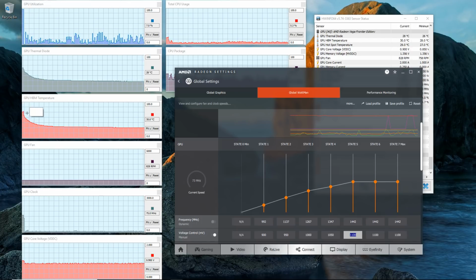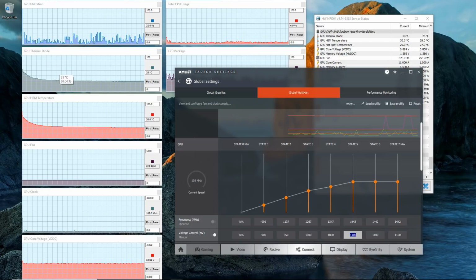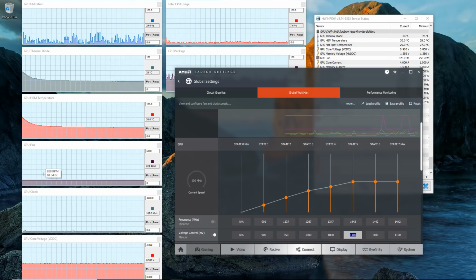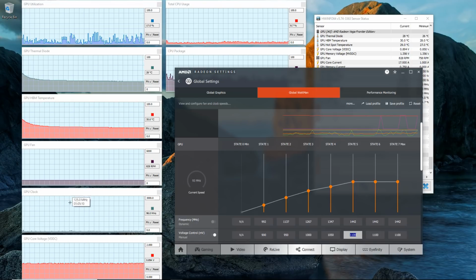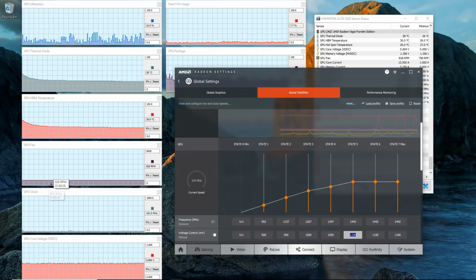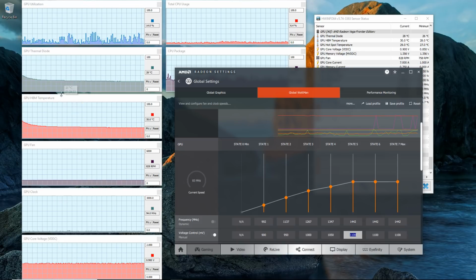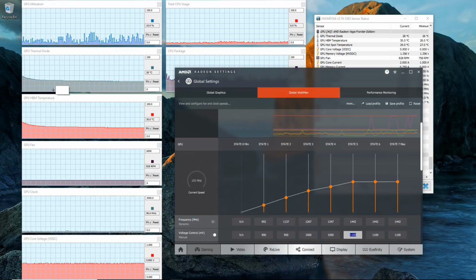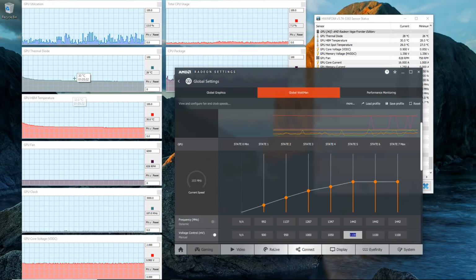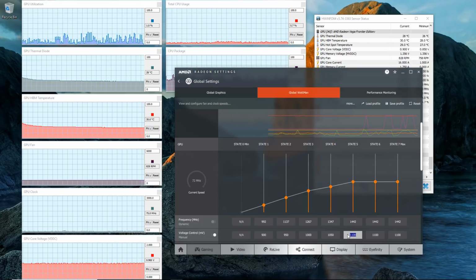And in addition to that, that thermal energy bleeds off into the GPU itself, and because it doesn't register the load, because it's paying attention to the clocks, the voltage, and also the temperature dial to some extent, it's not going to bump the fan up in response to that. So you'll see a slight increase on your GPU thermals as well as you drop your voltage.